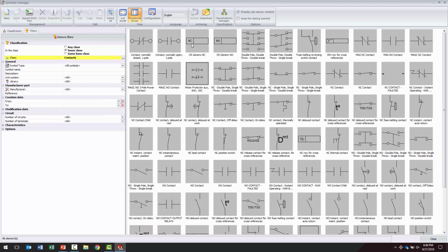I can put those into a table type format now that simply says normally open or normally closed. Doesn't show you the picture, but still will give you the accessibility of knowing whether something is spare, because the wire number won't be in this space, and it will all be blue, or whether it is being used, or whether it is not being used as far as being red or green.